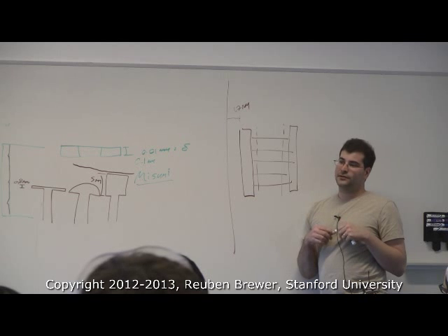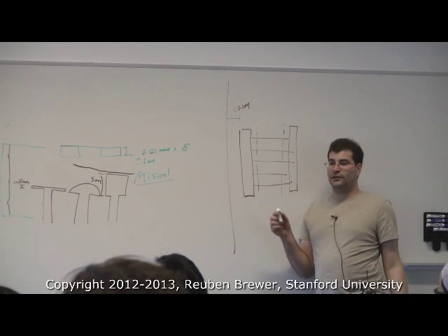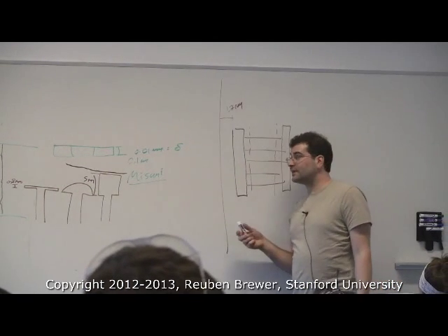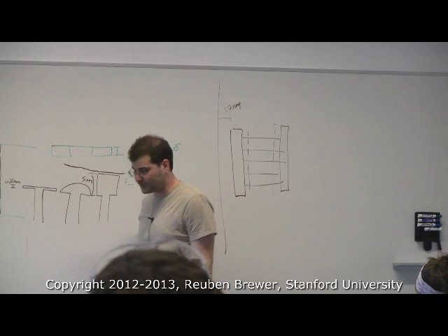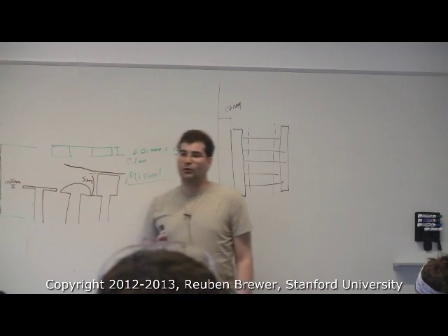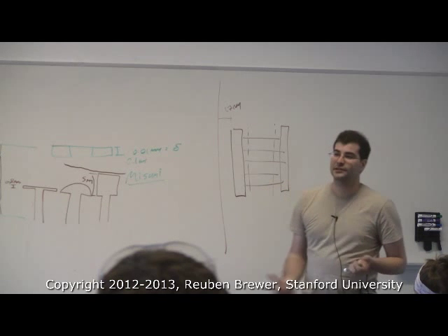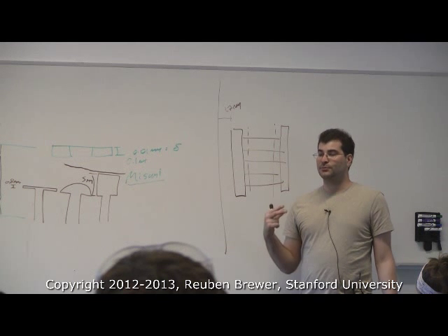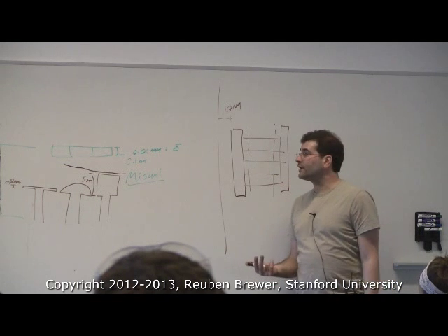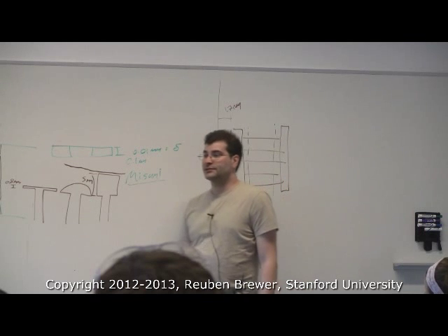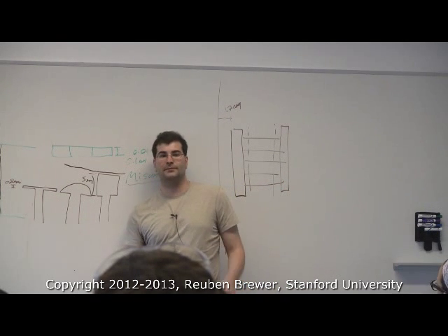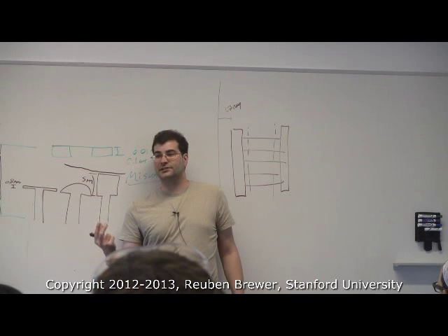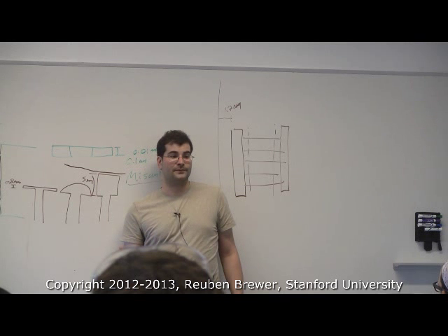But then I said to a lot of people, okay, so make that 1.7, and they're like, well, but there are no shims there, so how do I do that? And it occurred to me, an important thing to note is that you don't have something precisely located only if you have a dowel pin or a shim installed permanently as part of the robot. Half of the stuff I do is installing stuff very precisely with jigs or dowels or shims, and then immediately removing those jigs, dowels, or shims. Because if I don't need it for it to stay there in place, then it just adds weight, right?